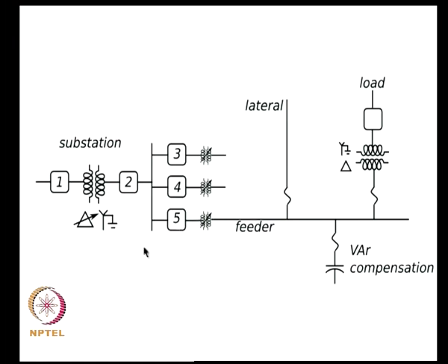You have circuit breakers. So, here I have indicated 2 breakers at the substation transformer. The actual transformer configuration would depend on your individual substation. You would have breakers feeding the individual feeders that radiate out from the substation. So, you would be able to say operate or disconnect or protect on an individual feeder basis.